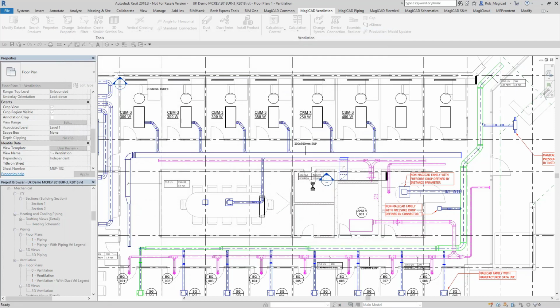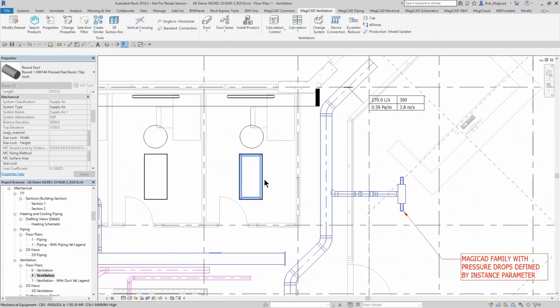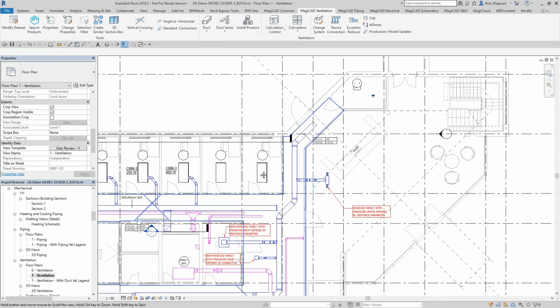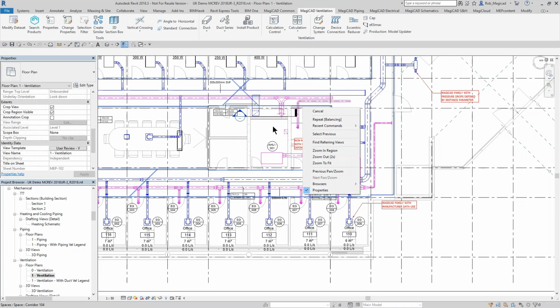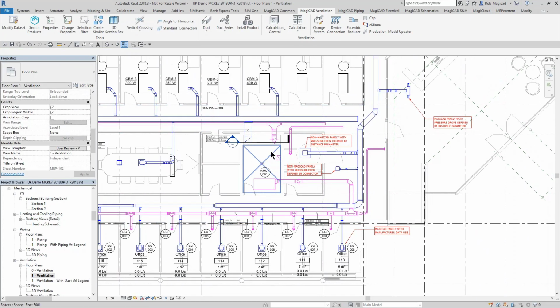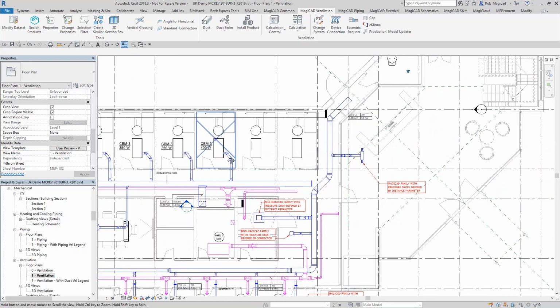So the simplified pressure drop is used, I would say, in most of the requests from this market, when people want to do a very early stage calculation and just want to throw some allowances in there, or their contract isn't down to do any kind of commissioning or balancing. All they want to do is select a fan, which is a flow rate and a pressure drop at a certain value, and that's it. So that's why we've introduced this calculation now.